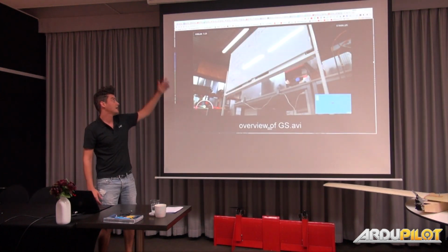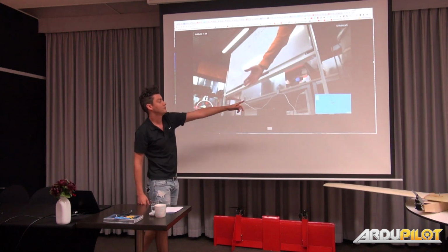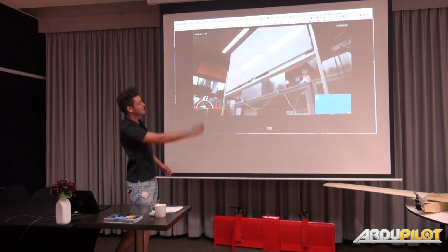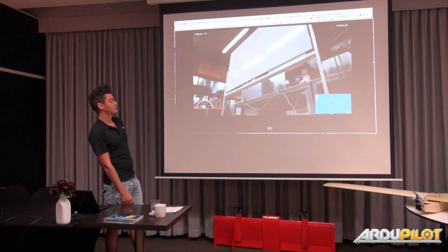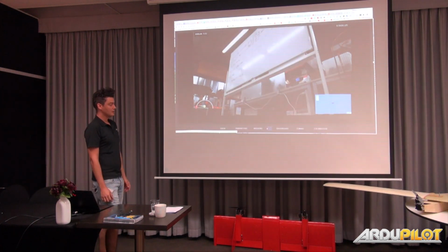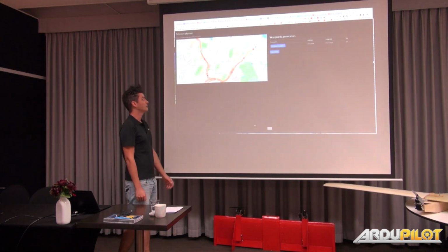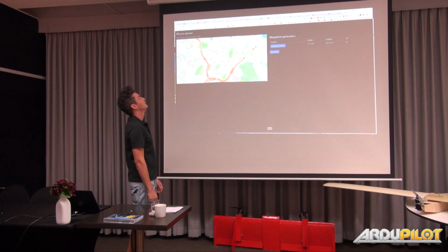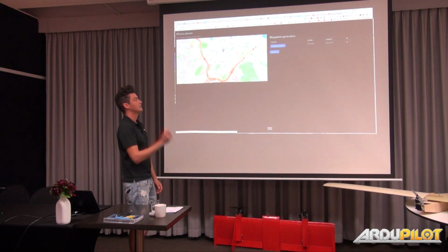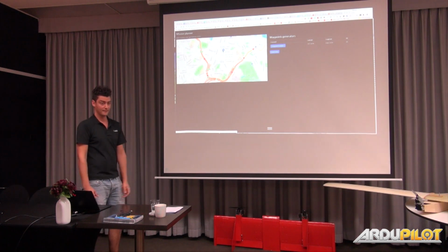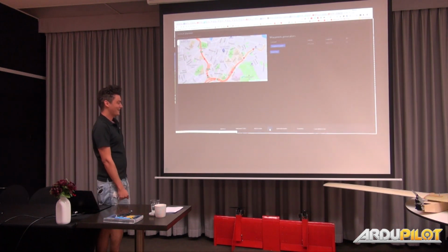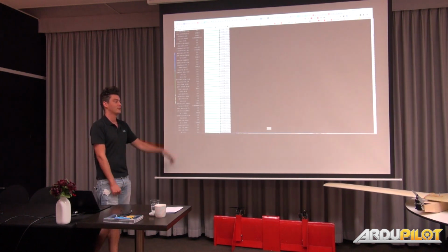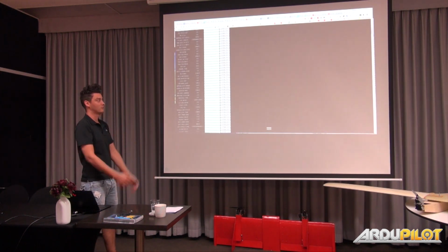So yeah, this is streaming altitude, ground speed, GPS location, it's flashing, and we also have the mode, that's me, stabilize mode. Yeah, it's really smooth. There's no delay. You have some mission planning. You can also double click on the map, and then you can tell it go there. It's called mission pointer. But it's web-based, right? And you also have parameters. You get all the parameters of the Pixhawk, and you can just change them from the web browser.